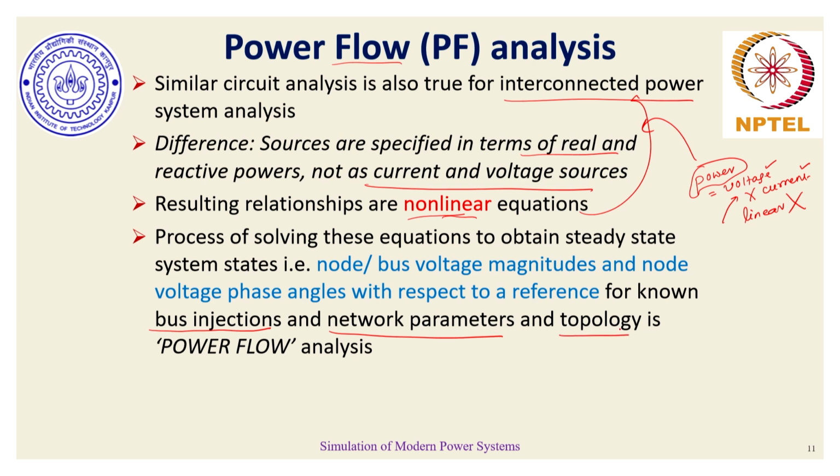The network topology is known: how many parallel circuits and series circuits we have. And if the same principle we used for circuit analysis is applied, the overall equations we would get would be nonlinear. Power flow analysis is basically an understanding of how to obtain these nonlinear equations and how to solve them so that we get our bus voltages or node voltages.